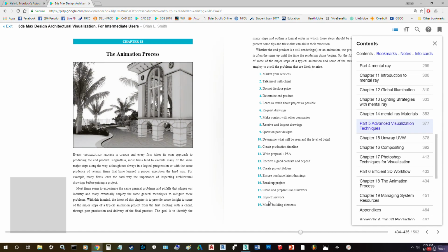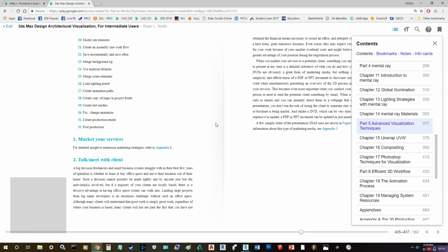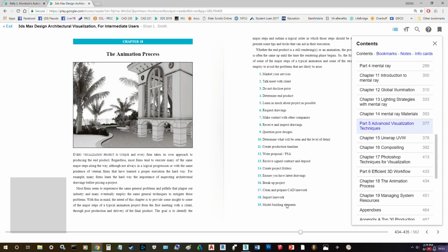In AutoCAD is recommended. Clean up your line work, which basically means whenever there's a curve or a break in your line that won't translate into 3ds Max, you have to manually correct that, which can take hours on end. And then you have to build the modeling, or build the building elements, which you basically transfer the line work over into 3ds Max, and then you can use each individual line work as long as you transfer it with the layer settings available, and then you can pick which layers you want after you've made your own line work and set up your own line work.